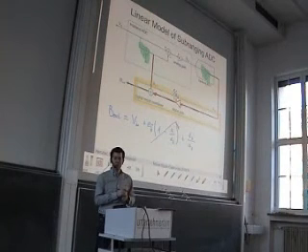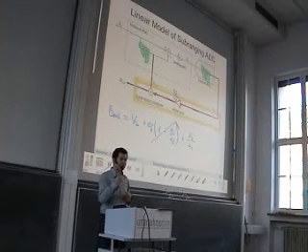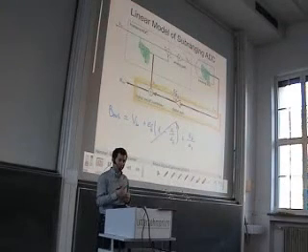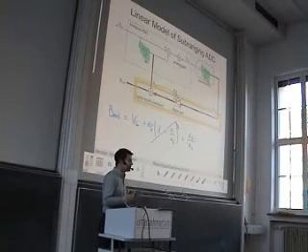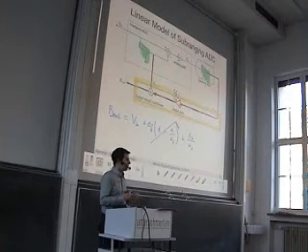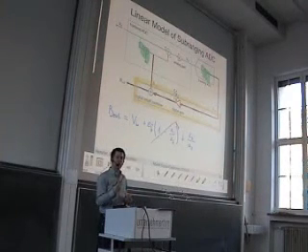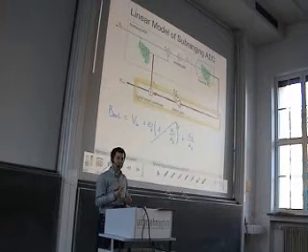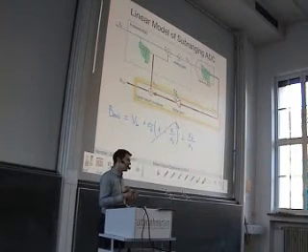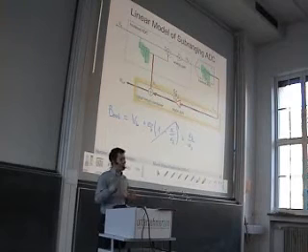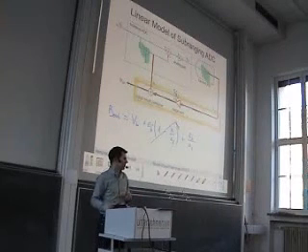And this is a difficulty, because one is a gain factor, an analog gain in an amplifier, the other one is a digital number. So the digital number can be designed very precisely and robust, but the analog gain can vary. So what we have to assure is that the digital gain always represents the analog gain.